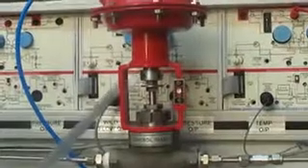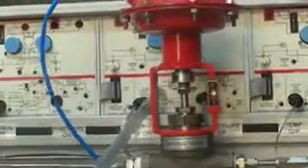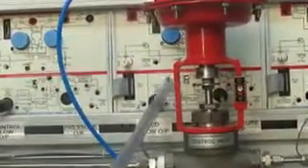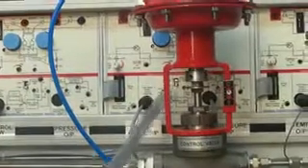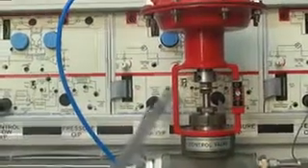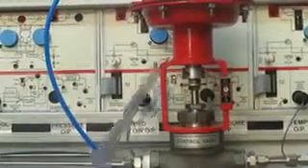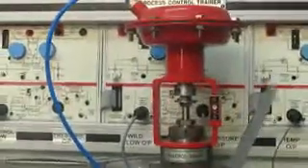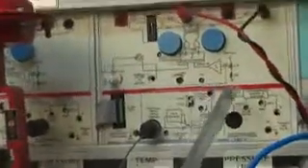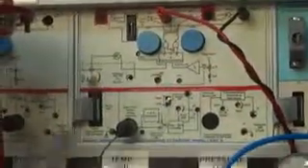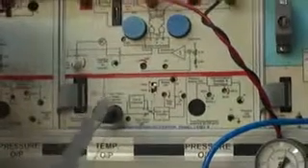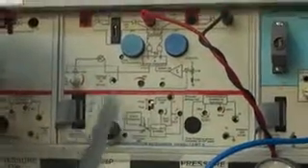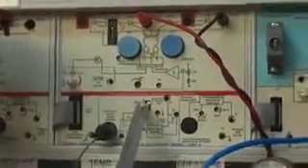There is one switch for temperature and flow. The bottom position selects flow, and if the switch is in the upper position, it indicates temperature. In the third panel we use the extreme right side for temperature output, so the switch should be in the upper position.